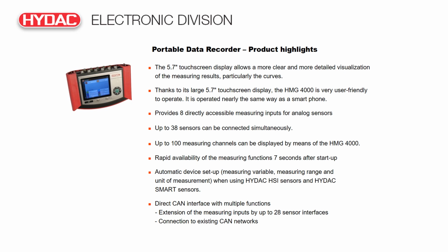The HMG 4000 also works with smart sensors, which are the AS1000 Aqua sensor and CS1000 contamination sensor, for example. In addition, it has the capability to connect to a CAN open or J1939 protocol and read the messages on the CAN line.